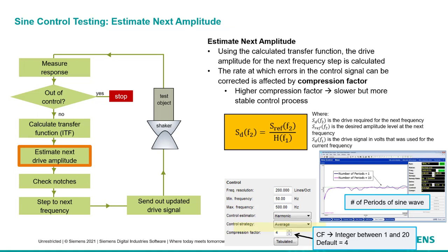And then we update the transfer function based on that calculation of the inverse transfer function. But sometimes, if we have extraneous responses, we don't want to calculate drive output from the DAC to the shaker, to avoid spurious amplitude estimations in nonlinear or resonant conditions.